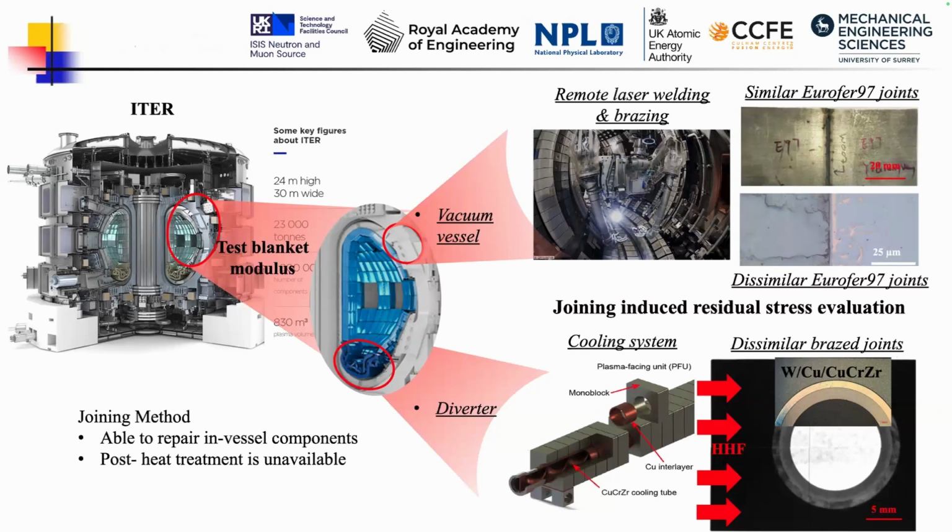In these scenarios, it would be interesting to understand the effects of the high heat flux, how the recrystallization will induce the residual stress, but also to understand the residual stress distribution across three distinct layers, with the plasma-facing tungsten to the copper chromium zirconium with the interlayer of copper. So Bing Zhu's talk is going to discuss these two effects on the residual stress distribution in this monoblock.